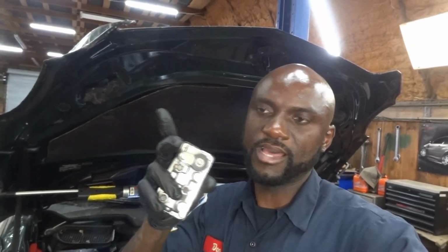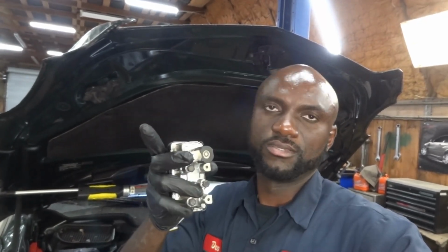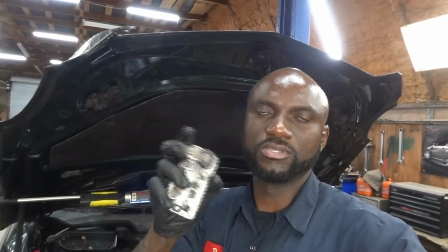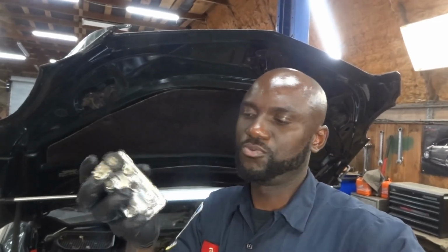Once you disconnect that, you're gonna connect the lever on the turbo to the lever over here on the new actuator and put the snap ring back, and you bolt these 3 bolts, and that's all, okay? And then you have to reconnect the electrical connector in the back and clear the trouble codes, and that should do it, okay?